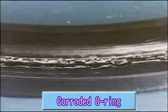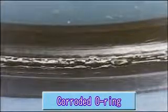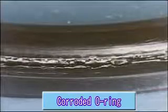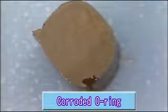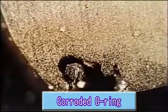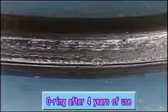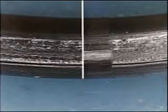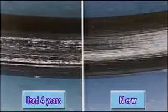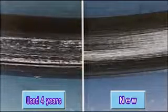This is an O-ring used in dirty oil. The grooved areas of corrosion are quite well defined. A vertical section of this part reveals corrosion caused by chemical reactions. If we compare the seal of an O-ring used for 4 years in a system that has clean oil with a new O-ring, we see no change in its ability to seal, although there has been some friction.